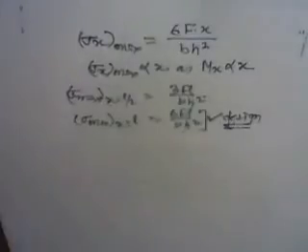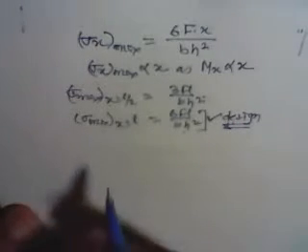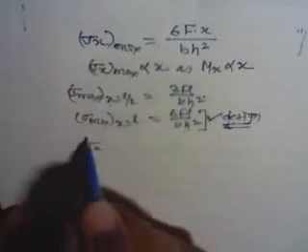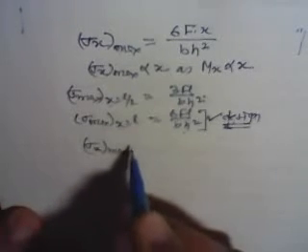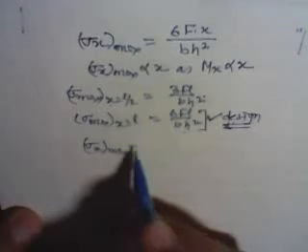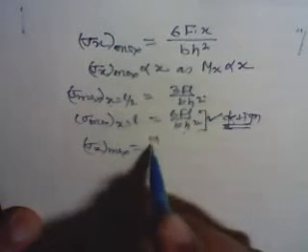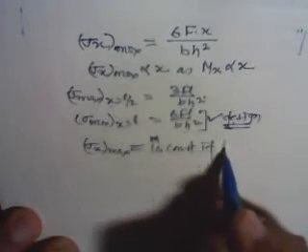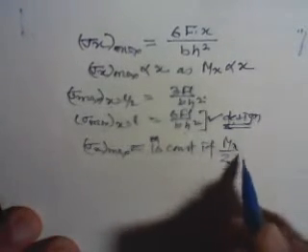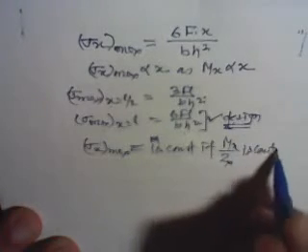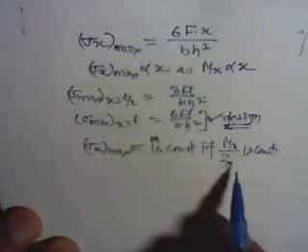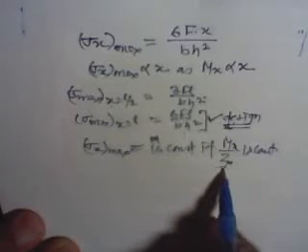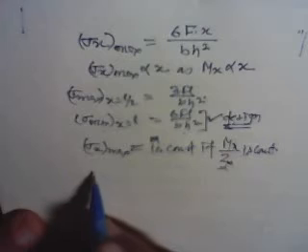So this stress is constant only if sigma X maximum is constant, and this will be constant if Mx by Zx is constant. So Mx by Zx will be constant only if Z is directly proportional to x.